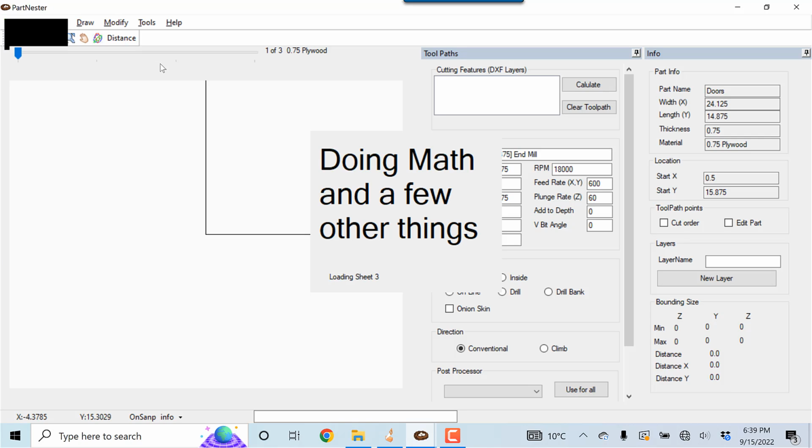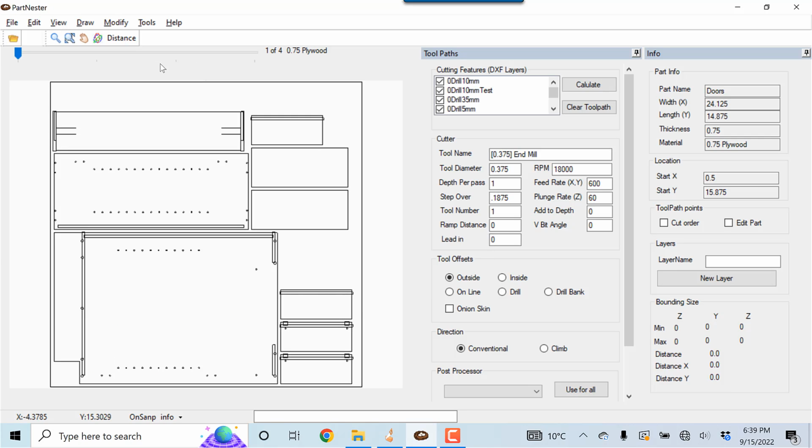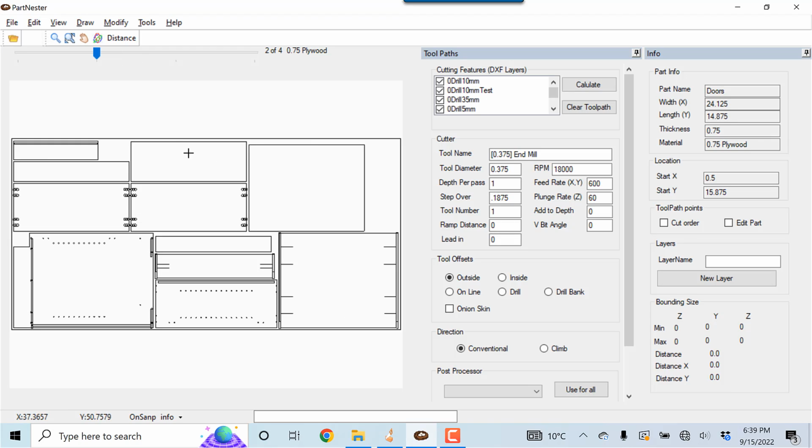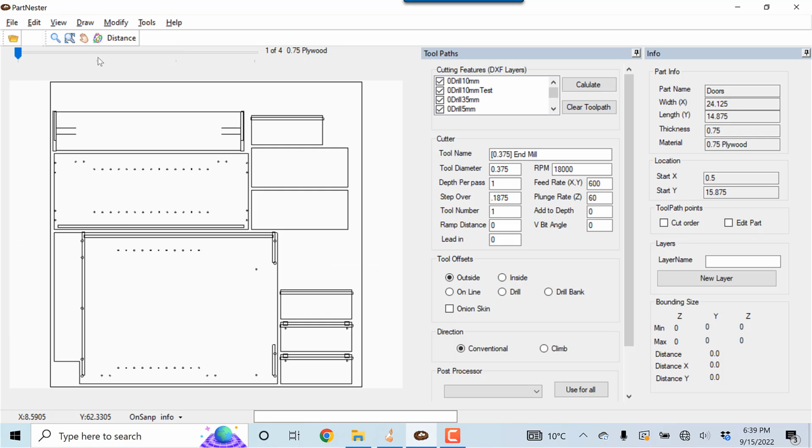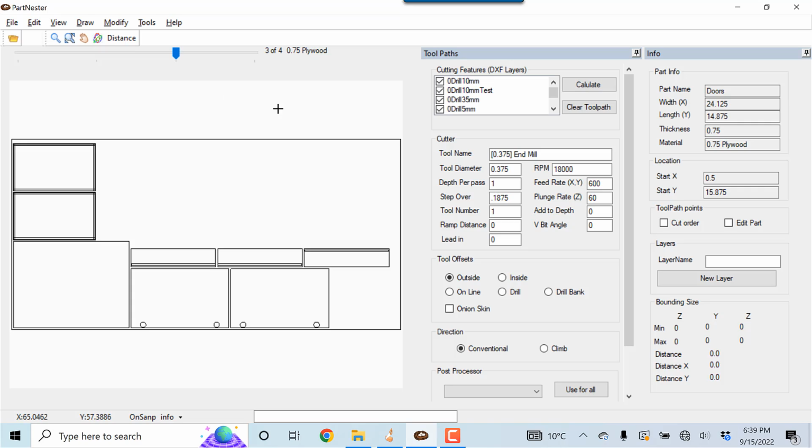The lower number priority sheet is the sheet that is going to get used first. So as we see, our first nested sheet is our 4x4 sheet that we've entered in as scrap, and then our next sheets are our 96 by 48. Since we are a partial sheet on the first sheet, it takes a total of 3 sheets for the 3/4 inch material.